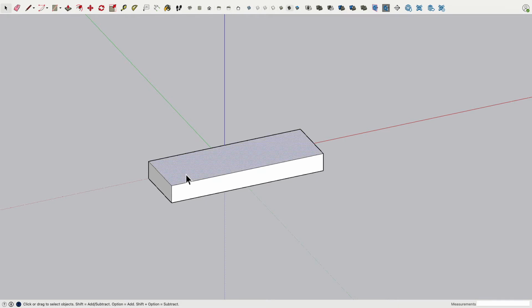Now, this is a very big block. And this area which I selected, I would like to core out a little bit. To cut something in, I would need to create a new rectangle here, and then select this and cut down.